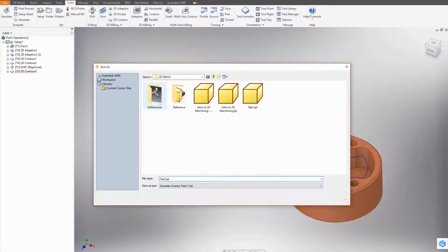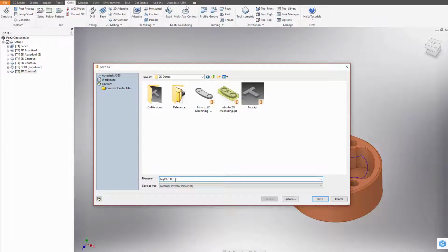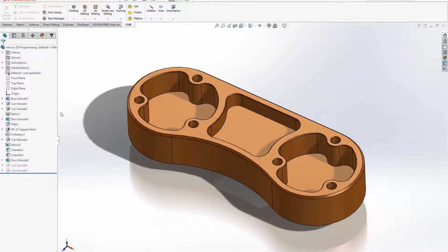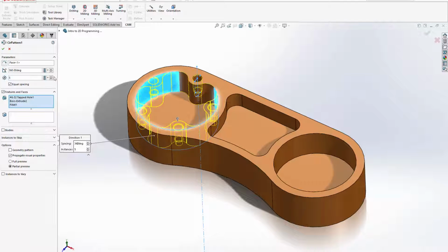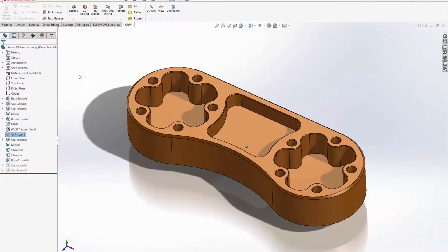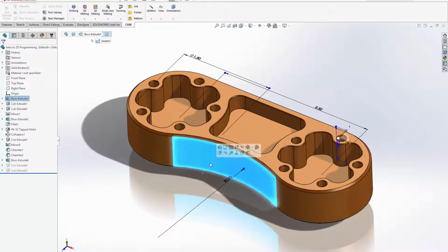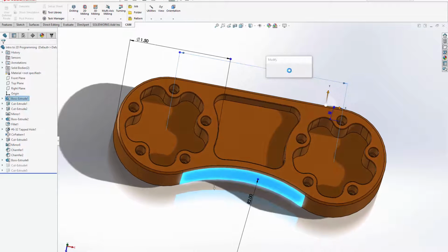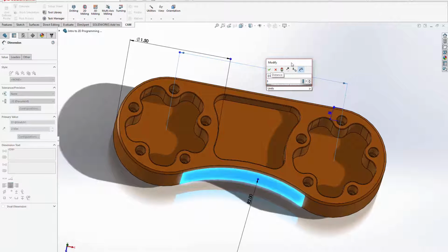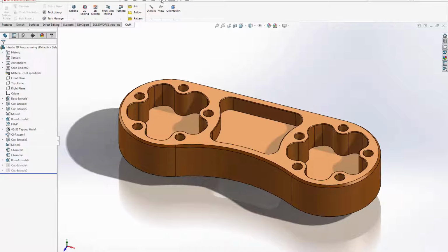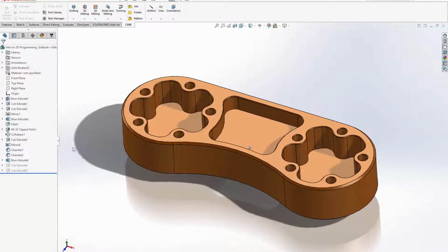So we'll just chuck this in here and we'll go AnyCAD demo, and then go back into Solidworks here. So let's change something like the circular pattern. So we'll edit that. Let's bump it up to 5 and see what else can we change. We can change this offset here to 3 inches rather. Increase the whole length of the whole part, and yeah, see how we go with that.